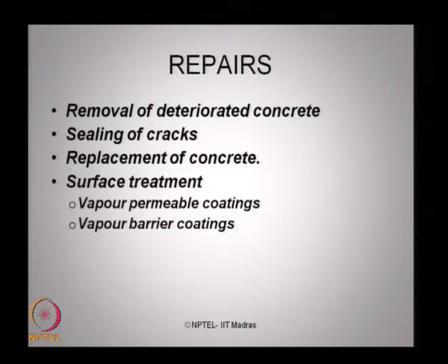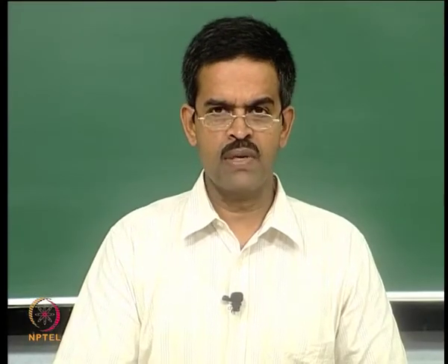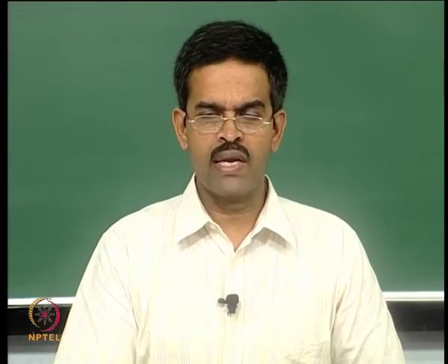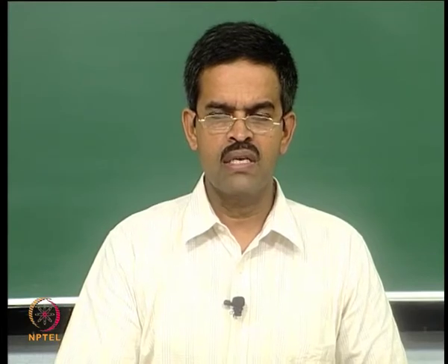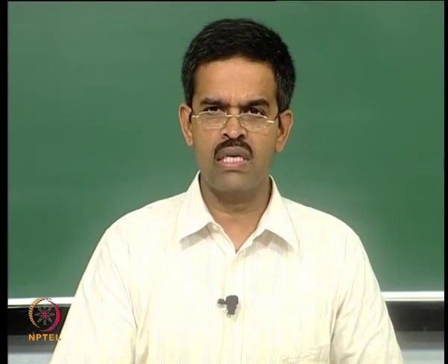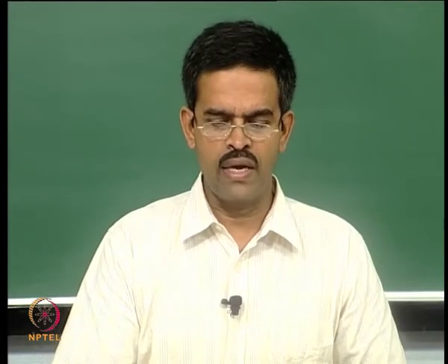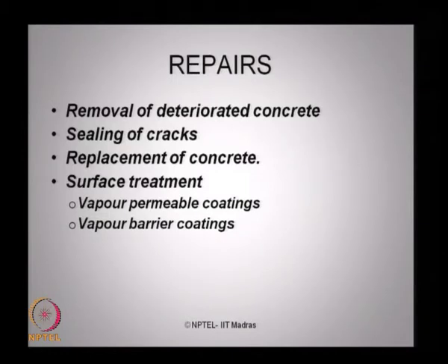Surface treatment is a cosmetic repair that people normally attempt for a short span of time to improve serviceability to a basic acceptable level. Surface treatments can be vapor permeable coatings or vapor barrier coatings. I am not degrading the surface treatments being done by practicing engineers to protect marine structures; they are all periodic maintenance. But if surface treatment is done essentially when you want to improve the quality control of concrete or to improve degraded concrete, it is not a good idea. Vapor permeable coatings can only give strength on the superficial side, whereas the internal integrity of these members would have been lost because of strength degradation.